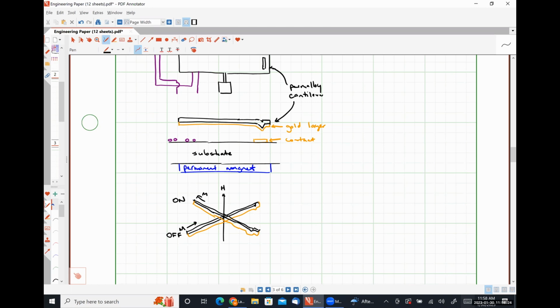Right. So these are used for higher current density applications. Particularly if we're considering integrated MOSFETs as our switches versus these, consider the current density that these can handle without undergoing, trying to remember what the right word is, the tendency of passing too much current to literally cause the wires to melt and move, which we talked about in our integrated circuits class, but the name of the phenomenon is escaping me.